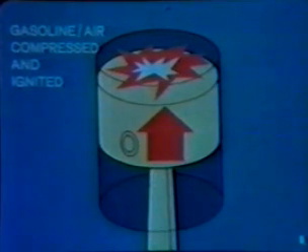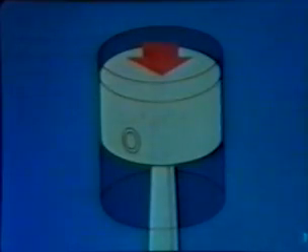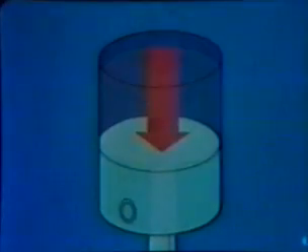As the gasoline burns, it releases gases that have a great tendency to expand. Expansion of the gases causes a very high pressure above the piston, pushing the piston down very forcibly in the cylinder. Therefore, as the piston moves, the expansion of the burned gases then becomes power. Since the piston is confined in a straight cylinder, it moves in a straight line.